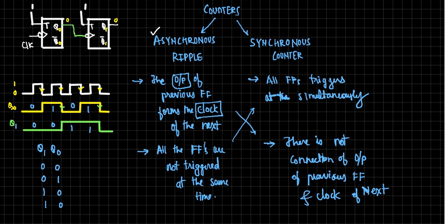That's why it's a ripple or asynchronous counter. It is changing the states, and it's counting in binary. So it's a binary counter, and it is counting 2 bits, right? So it's a 2-bit asynchronous counter, right? Asynchronous, but what edge? Negative edge. So let me write the full name of this. So it becomes 2-bit.